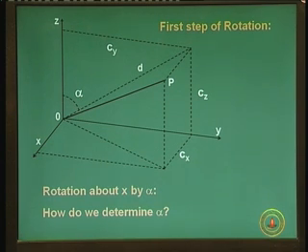When you project OP on the zy plane, remember, we are not going to actually project it, it is just a projection. That means, if I rotate OP by an amount alpha, which will bring OP onto the xz plane, you can equivalently visualize that this diagonal line, marked as a distance D on the zy plane, will coincide with the z axis. So, when you turn OP and coincide it with the zx plane, the line marked D will coincide with OZ. That is what will happen.